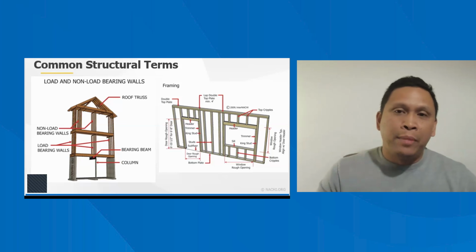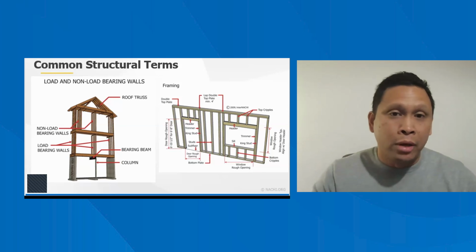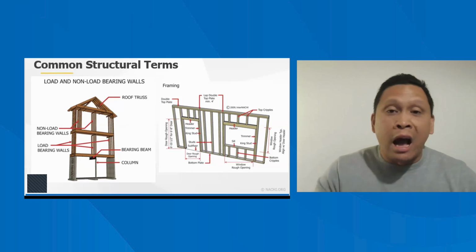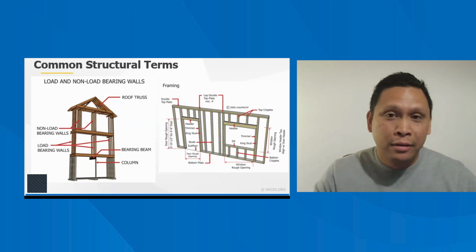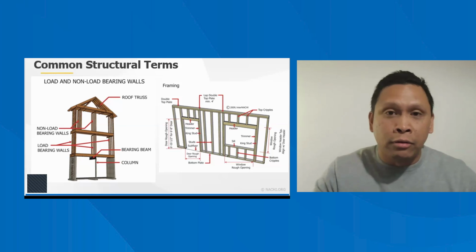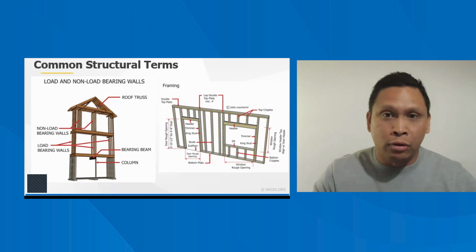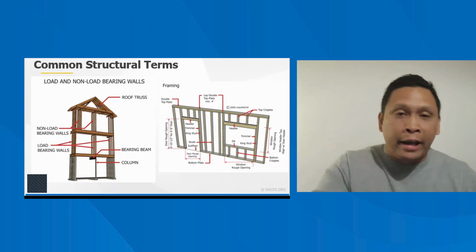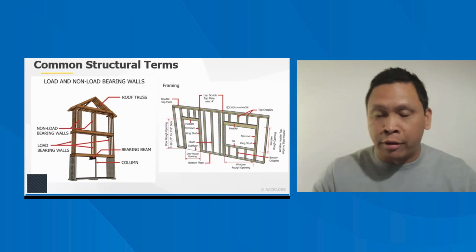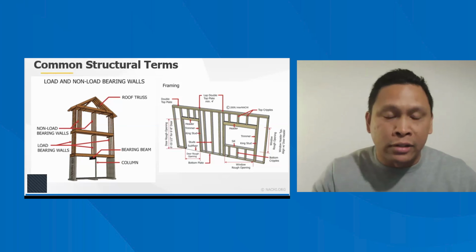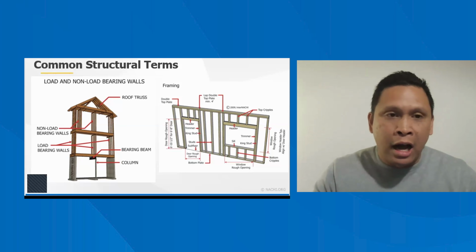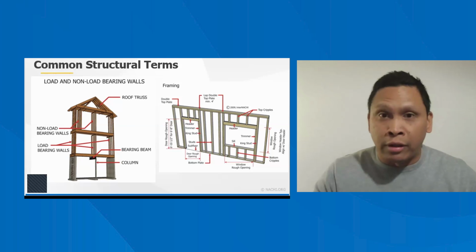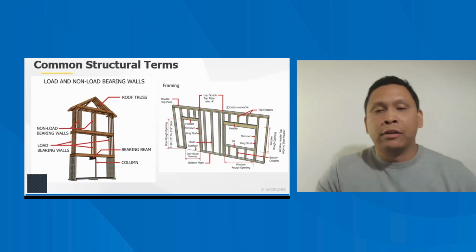But I share that story because if you're moving really, really quickly to try to accommodate the volume, you may get unlucky and not see that stair step crack, even though it's on the front side of the home. And you may also, I don't know how, but you may also miss that the floors are bouncing on the second floor. But when I was shown the front elevation of the home, I could instantly see the stair step crack. So it's important. Take your time, and I think that's the right thing to do when we go through homes. So okay, enough said.